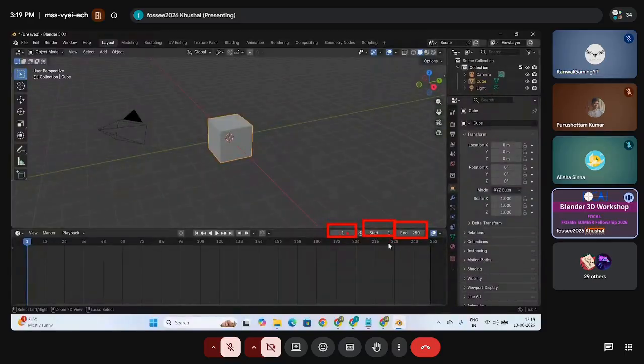And now you are at frame 1. You can see the blue line is there. That is our time cursor. We already know that in Synfig Studio, the time cursor is the blue line. This is now at frame 1. Suppose I click on 24, you can see my time cursor is at 24 now. Now at 72, 120, 156. In this way, you can move your time cursor. So this is our time frame panel.